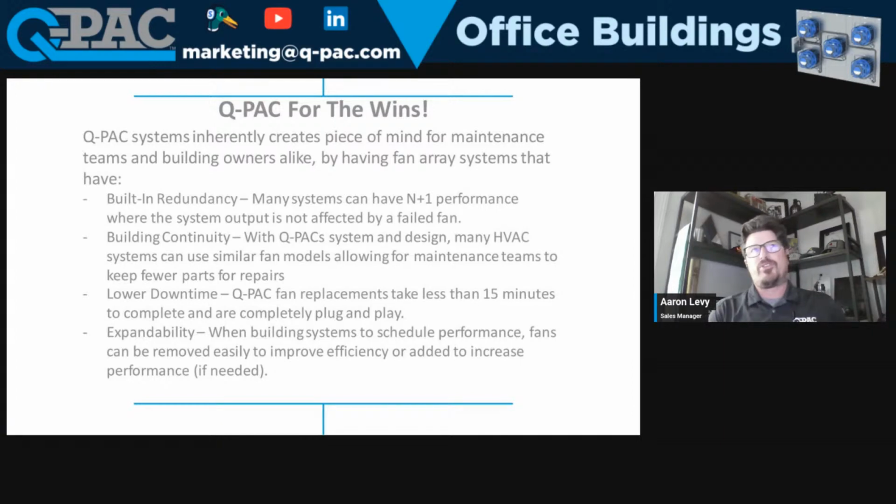And this is something that we talk about with Q-PAC: the way it was designed and engineered is that we have that built-in redundancy. If a fan does fail, the rest of the fans in the system will spool up to compensate for that lost fan. It takes about 10 or 15 minutes to change out a fan, so they're never really down for very long.